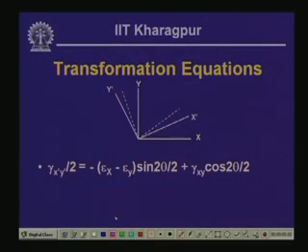Now, let us evaluate the value of the shearing strain with reference to x dashed y dashed axis. As we know, shearing strain is the angle which is changed from its original 90-degree position. If we have two reference axes which are at 90-degree with each other, the shearing strain causes the change in this 90-degree angle.